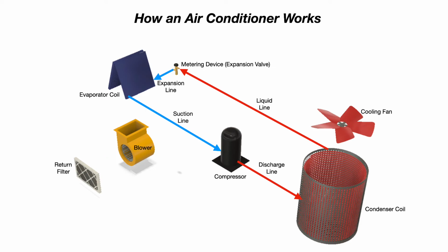Then that heat energy is transferred via the refrigerant to the indoor coil inside your house. The blower fan blows over that warm indoor coil, and you get warm air coming out of your supply registers. And then the refrigerant flows back outside, picks up more heat energy, brings it back inside, and the process repeats itself.